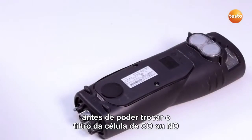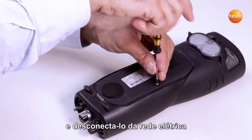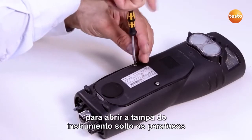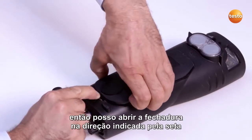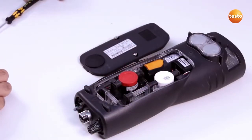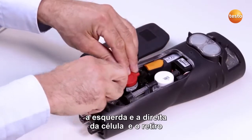Before I can replace the sensor filter from the CO or NO sensor, I must switch off the Testo 340 and disconnect it from the mains. To open the instrument cover, I undo the screws. I can then open the clip in the direction of the arrow and remove the service cover. I pull out both hose connections on the left and right of the sensor and remove the sensor.